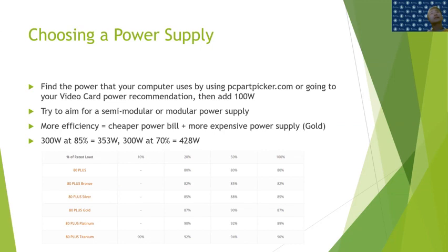The power supply actually uses more energy from the wall than it outputs, and that's because power supplies are only a certain amount efficient, as you can see in the example above the table. In the table below is the 80+ certification, which is basically used to designate how efficient a power supply is. A power supply certified 80+ Silver, according to this chart, would be 88% efficient at 50% rated load.